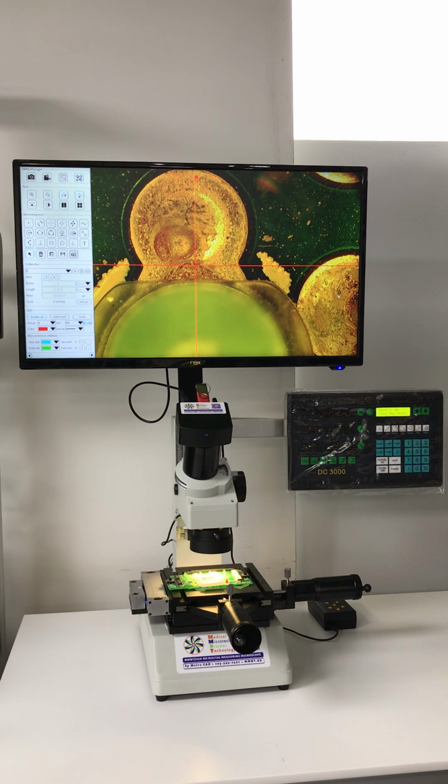You can save up to 100 features or measurements, and what you will do is give it a number. So let's do 1, press enter, and it'll save, and then you'll save your measurement, press enter, and finish. To bring it back up, press the recall button, press 1 to bring up the feature, press enter, and there it is. This can also be hooked up to a printer and you can print your icon as well. Press finish when you're done and it'll bring you back to live.